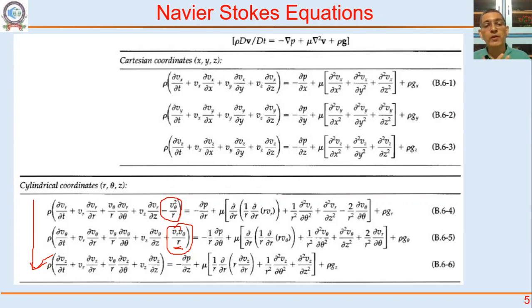There are something called Coriolis mass flow meters that actually measure the magnitude of this force. For that, we make the fluid go in the r direction, and we also give it rotation, allow it to go around a bend, and then you measure the force on the bend. That's how the Coriolis mass flow meters work.